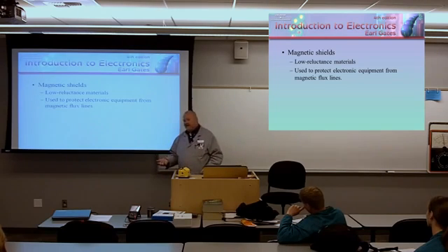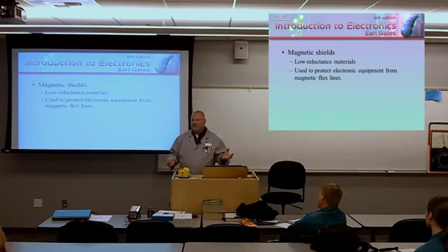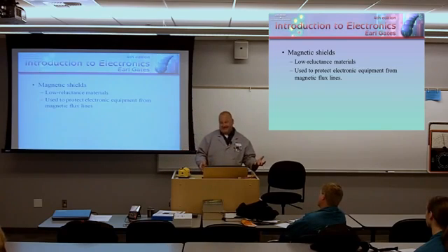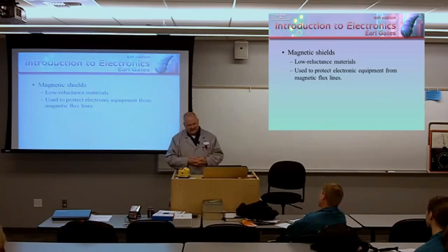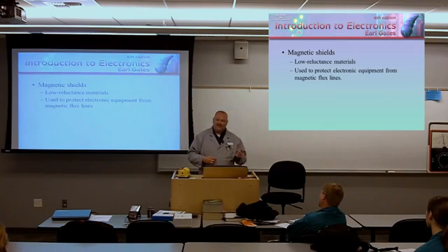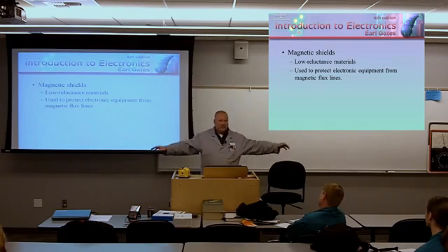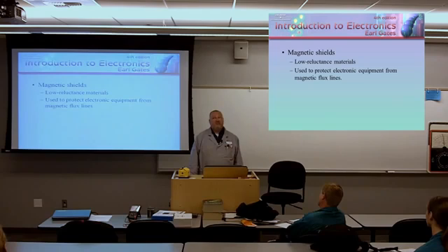One of the manufacturing trends now with aircraft, though, is not to build airplanes out of aluminum, it's to build them out of composites. They're not always using carbon, they're just using various composites. One of the things they're doing on aircraft now, especially control surfaces, flaps, and ailerons that control the roll of the aircraft, is making these out of composites. So if you get struck by lightning, it's quite simple. The lightning gets in there, has nowhere to go, and it blows the control surface apart. Not good if you're in the airplane, because now you're going to lose control since you don't have the ability to control the aircraft anymore.